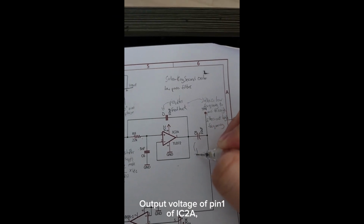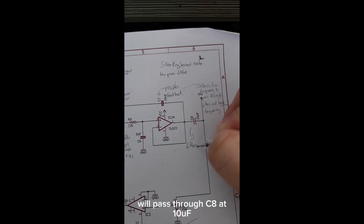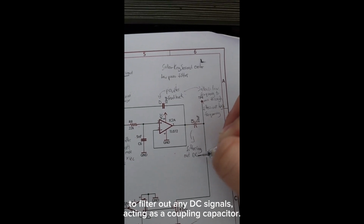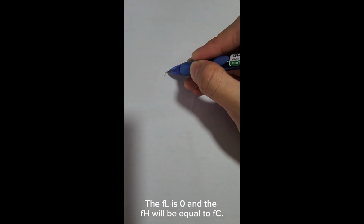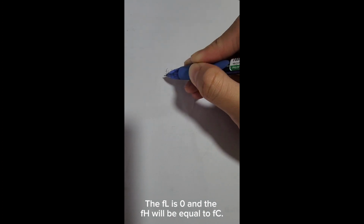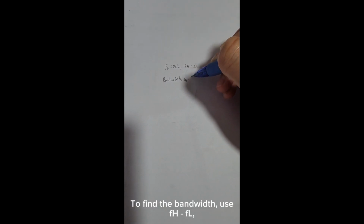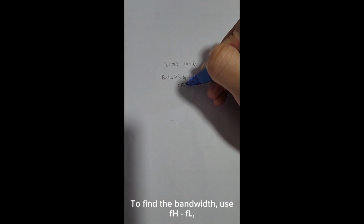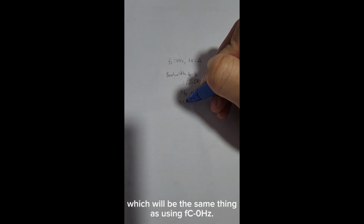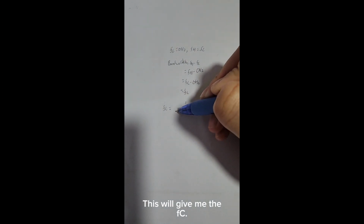Output voltage of pin 1 of IC2A will pass through C8 at 10 microfarads to filter out any DC signals, acting as a coupling capacitor. The low frequency will be 0 Hz, and the high frequency will be equal to the cutoff frequency. To find the bandwidth, we'll use the high frequency minus the low frequency, which will be the same thing as using the cutoff frequency minus 0 Hz. This will give me the cutoff frequency.